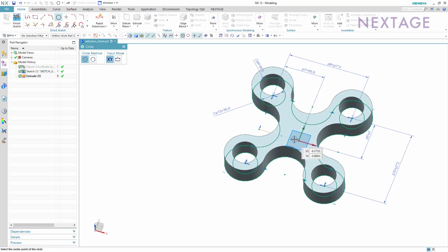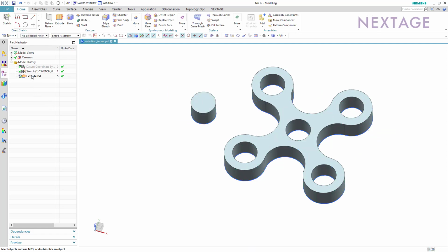I'm going to make the circles just as before, and one outside. And the reason why I had the one outside before is because now you'll see that my extrude is using all the curves that are residing inside my sketch, and therefore it will subtract this region here because it's going to use the sketch of the curve, the circle here, and it's going to add the circle out here to the selection of the extrude, because my extrude remembers it's looking at the entire feature and not just particular curves from that feature.